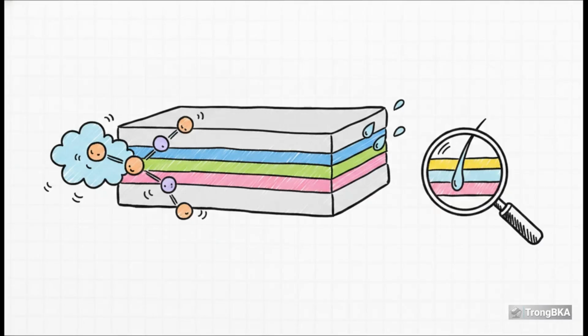And those microscopic barrier layers I just mentioned, they're made of highly specialized polymers. EVOH, which is an ethylene vinyl alcohol copolymer, is an absolute fortress against oxygen. And PVDC, polyvinylidene chloride, is incredible at stopping moisture vapor. But here's the thing, these materials are super difficult to process and they're expensive. CFD allows us to design equipment that spreads these polymers into layers thinner than a human hair. This lets us utilize their barrier properties efficiently, without wasting a drop of expensive material.